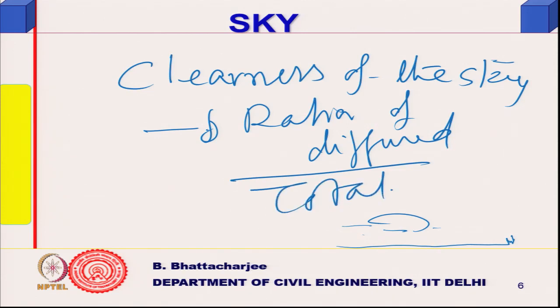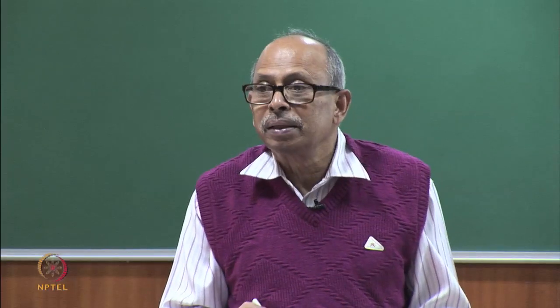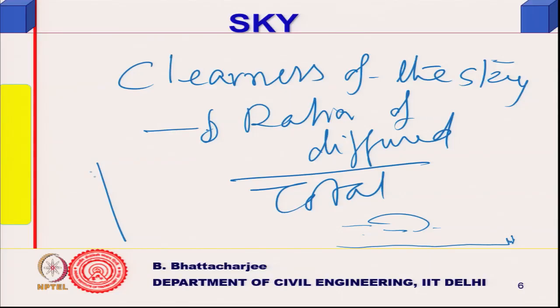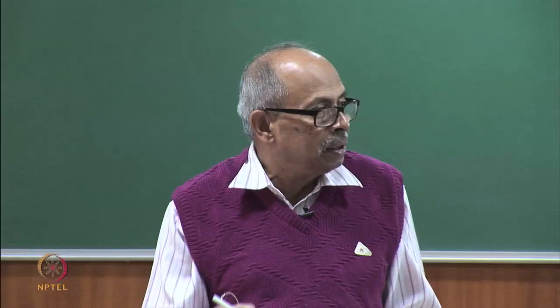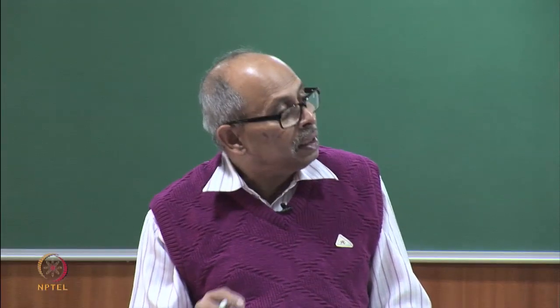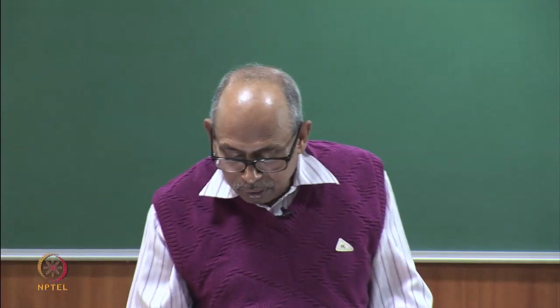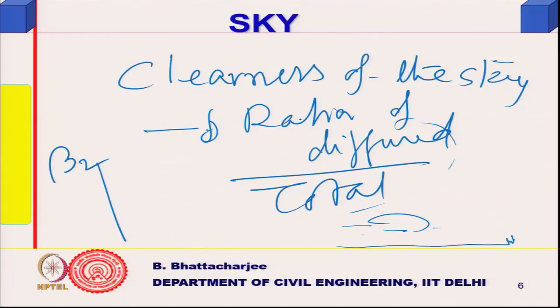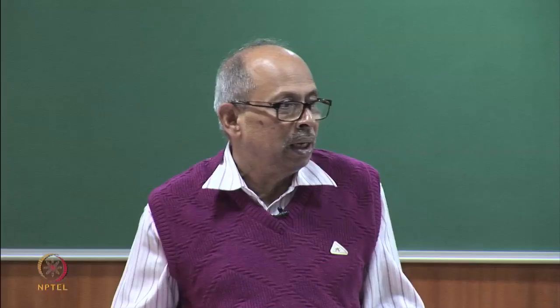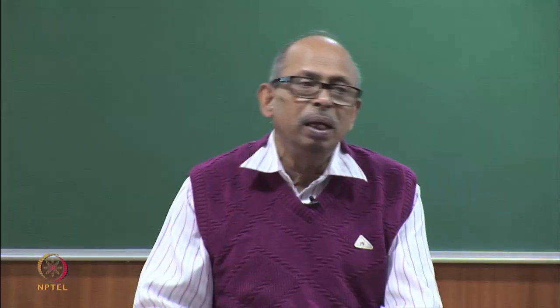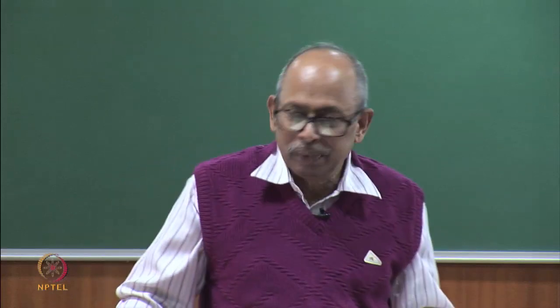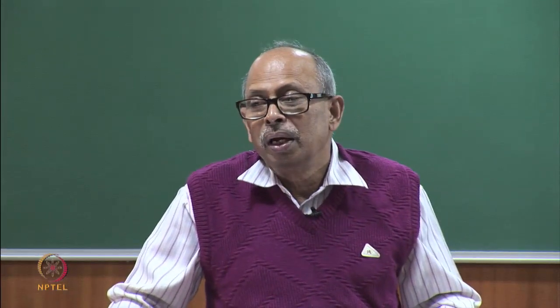So, zenith brightness, which I am calling Bz, I can relate to this. One of the unknowns there is Bz and ABCDE. So, Bz and ABCDE I should be able to relate to this term, clearness of the sky, and that also has been done, and again it is validated for only certain locations in the globe, not throughout.